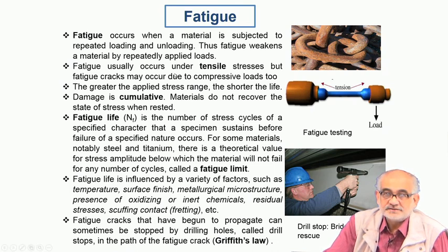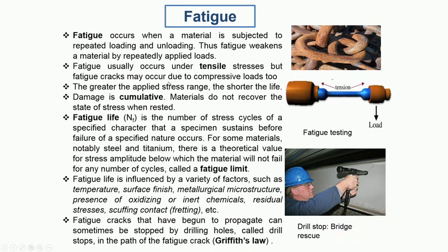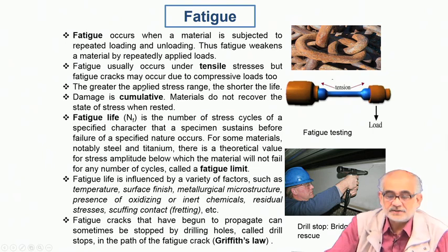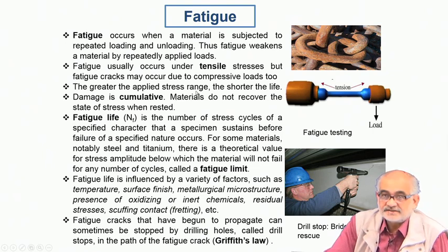We all know that whenever we have a crack or any amount of discontinuity on the surface under tensile loading, it is likely to undergo accelerated failure or accelerated crack opening. So what is important is that if the overall condition on the external surface is tensile in nature, then damage due to fatigue can be more harmful or more likely.